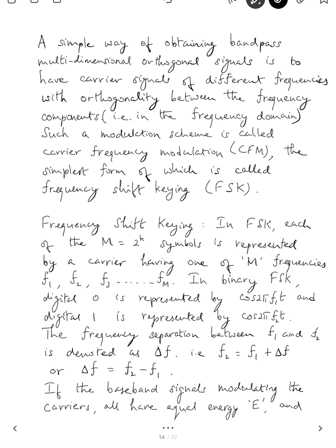The amplitudes are the same. The only thing that is different between the signals is their frequencies, and by virtue of their frequencies we can make them orthogonal. So we have to choose the frequencies appropriately, with the same cosine wave or carrier signal but of different frequency.